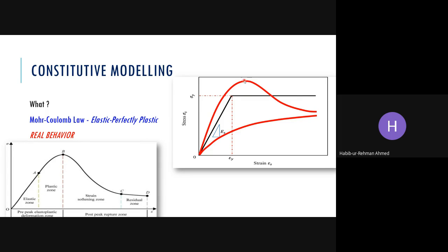So you will have a higher peak, and then dilation, and there is a compression, and finally it reaches one point. And if we look at loose soils, they keep on compressing themselves and reach over here. So there is no dilation. This is another very specific property of the soil that makes it different from other materials.